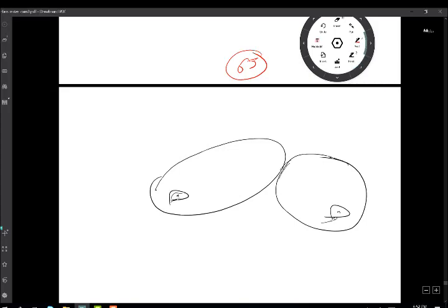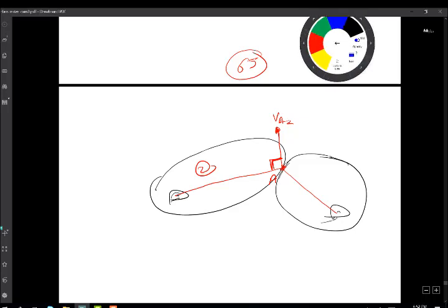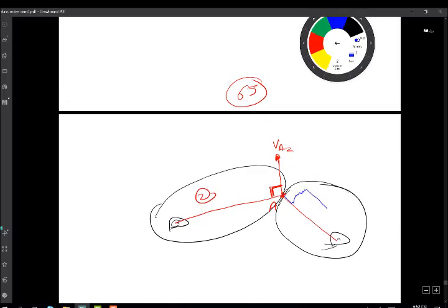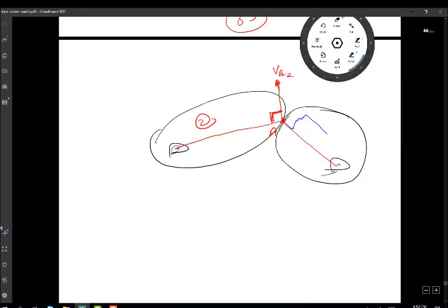Now you can tell, if I find where the point of contact is and connect those together, then the velocity is not the same, because the velocity on link number 2 is perpendicular to this line, right? So this is VA being on 2. Let's call the point of contact A. Being on the other link, I'm going to give it a different color.